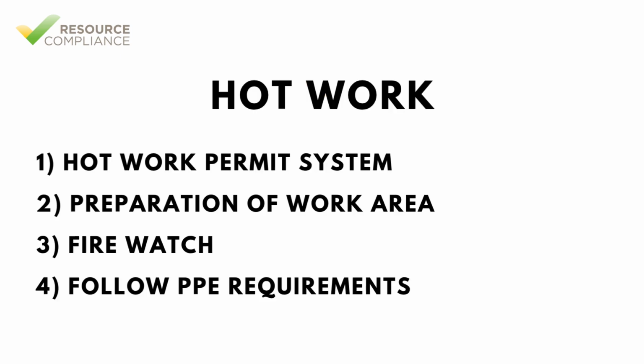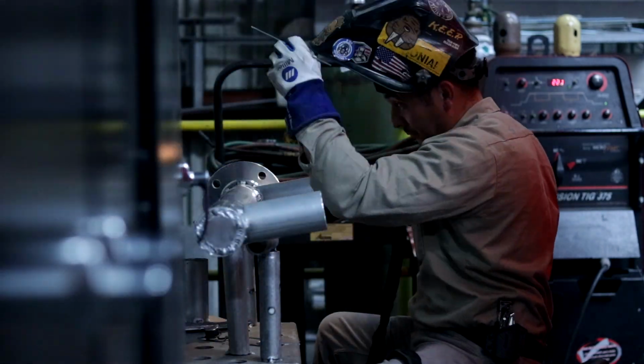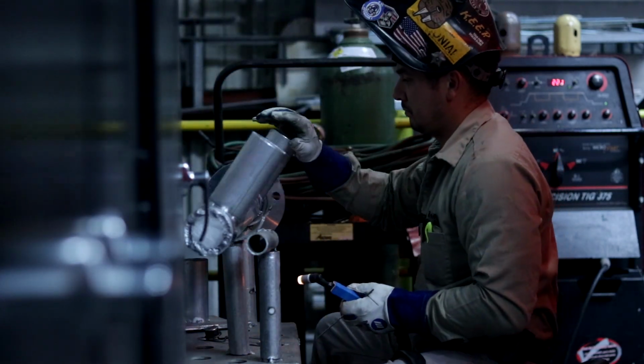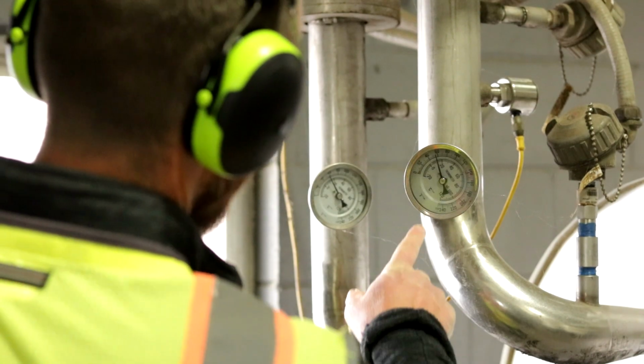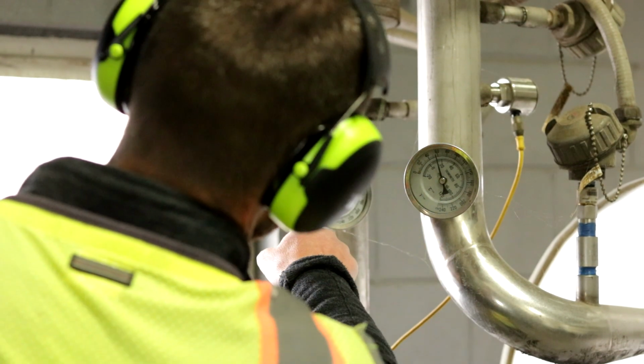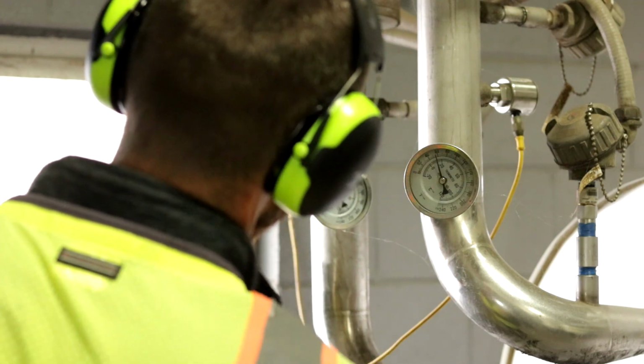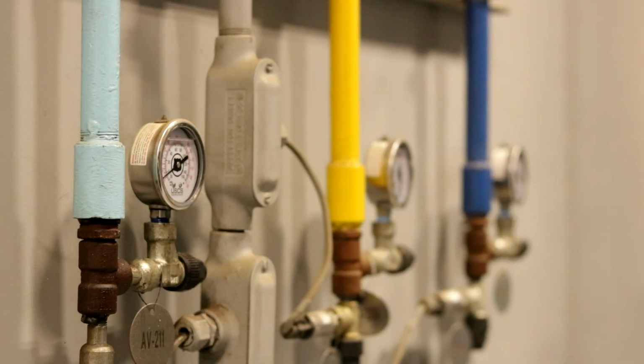Wear flame-resistant clothing, welding shields or goggles, gloves, and hearing protection as required. Verify that refrigeration equipment is de-energized, depressurized, and properly isolated before beginning work. Never perform hot work on lines or vessels that may contain refrigerant or oil.